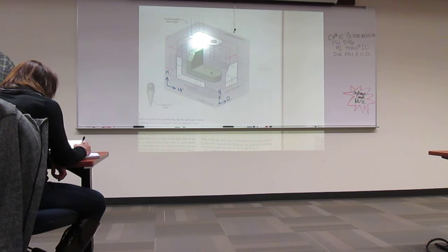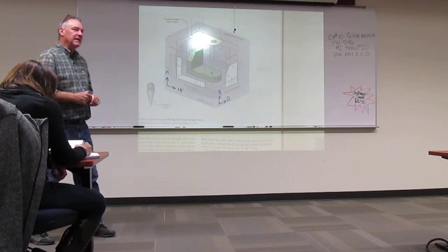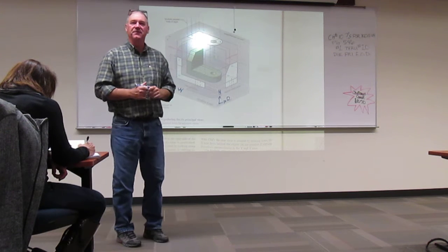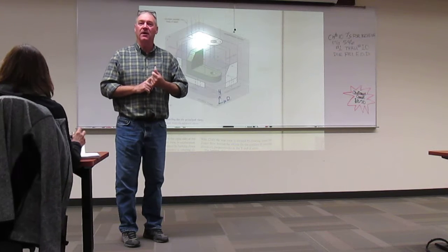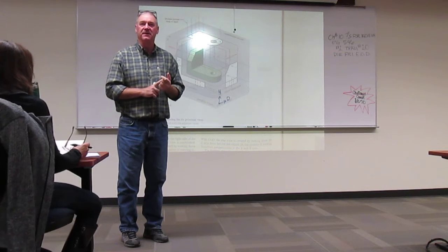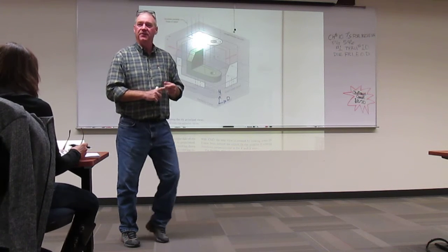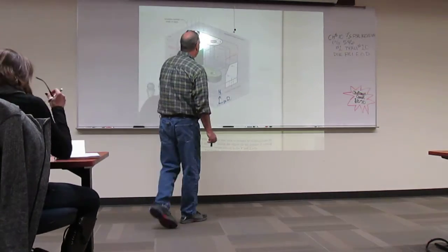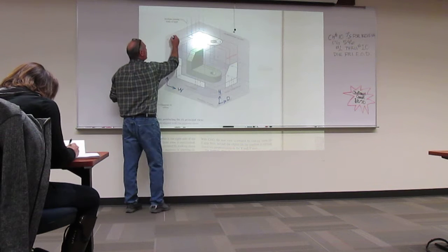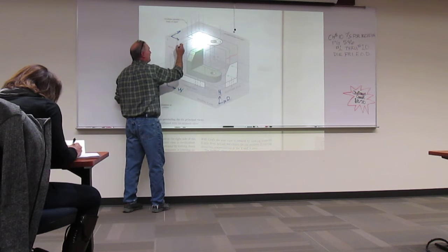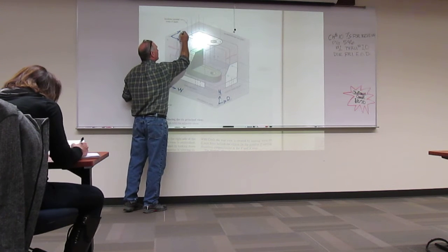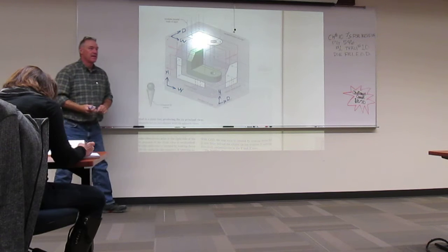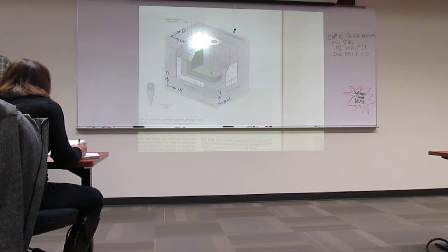If you might have noticed by now, what we're really talking about is three dimensions, right? Height, width, depth, and how we are going to describe them using orthographic projection. We do that through these planes. We have one other plane left that creates our other two views. This is a horizontal plane up here. And if I had to have dimensions on the horizontal plane, they would be width and depth. And that will create the top and bottom views.